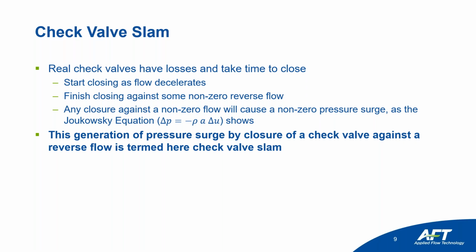That's also a concern, but this specifically is about the fact that check valves take time to close, and because they realistically take time to close, flow will actually reverse through the check valve before it closes. So an ideal check valve prevents all reverse flow. A realistic check valve does not. You have some reverse flow through the check valve when it closes, and just because of the Joukowsky equation, as we see, the pressure surge there is non-zero. So we're calling that generation of pressure surge check valve slam.